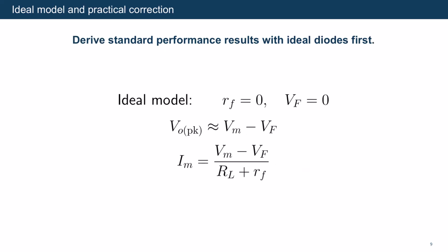We first derive the standard waveform factors with ideal diodes. This keeps the shape mathematics clear. In a practical circuit, one diode drop appears in the conducting path, and forward resistance reduces the peak current. We will include forward resistance explicitly in the efficiency expression.